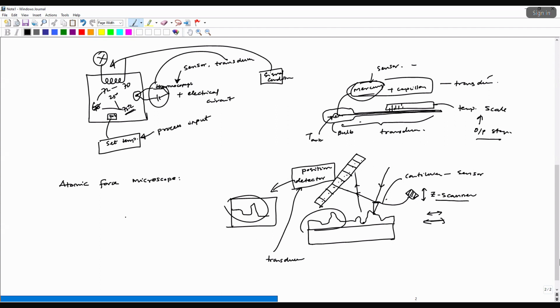Now, when you take a photodetector, let's say there is a set of photodetectors. When light falls on them, typically light has a Gaussian profile, where the maximum intensity of light will be at the middle. So when this light falls on a particular detector, it peaks there, but there is also some stray signal which falls on the detectors to the left and right.